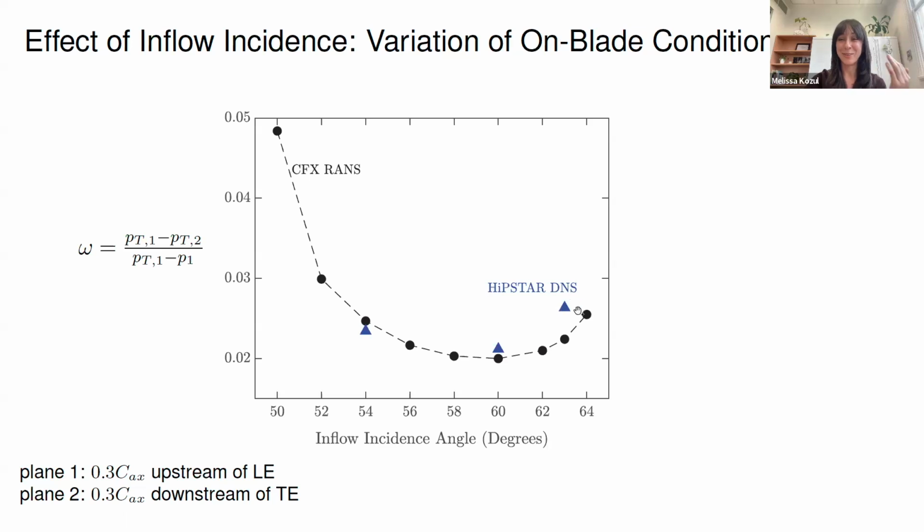And obviously we believe ours is correct, because what the RANS is doing is mispredicting the flow separation, for example, or mispredicting where the flow is transitioning from a laminar to a turbulent flow, which we'll see in a moment. So already there are issues, and this is just the smooth blade, and actually there are no adequate models for that riblet case, which we're going to look at.